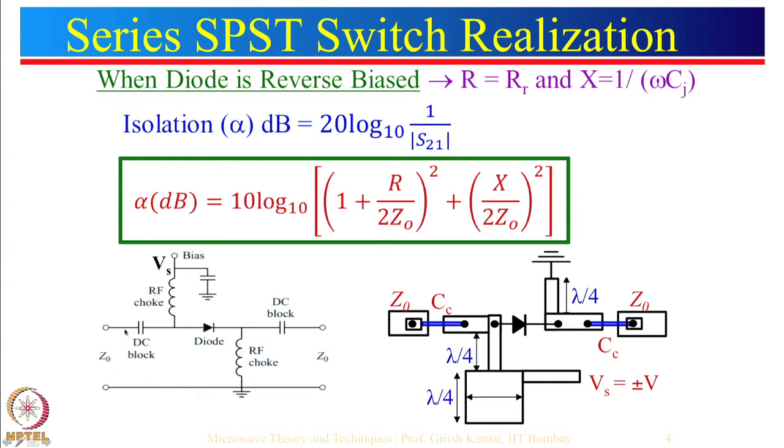So this is 50 ohm, the impedance should be less than 5 ohm, but even if you take Z equal to 1 by j omega c as even 0.5 ohm or so, it is good enough. Anything between 0.5 ohm to 5 ohm is recommended. So you should know the frequency of operation at which you are designing a switch, and accordingly you calculate the value of the capacitance.